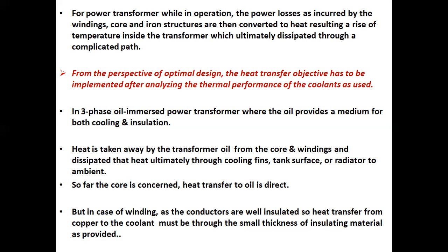So far as the core is concerned, heat transfer to oil is direct. But in case of winding, as the conductors are well insulated, heat transfer from copper to the coolant must be through the small thickness of insulating material as provided.